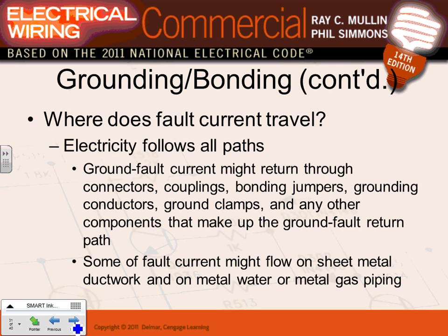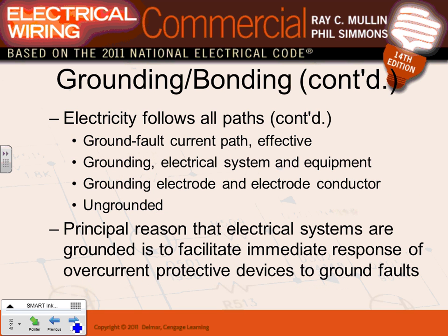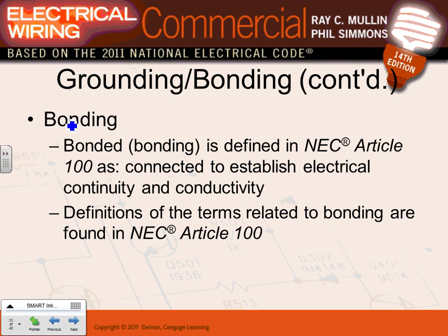What does a fault current do? This is just analyzing, guys. If you have a ground fault, the current goes right through you and through the equipment and all the paths. Electrical fault is when we have electricity flow in every path. So if you have a ground fault, anything metallic between 2 points will be carrying that ground fault. So they have to be bonded together. I'll talk about this bonding.